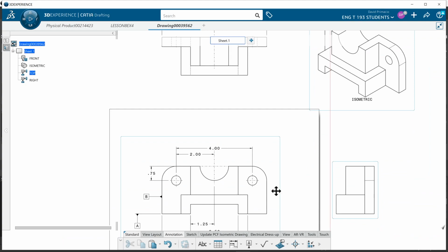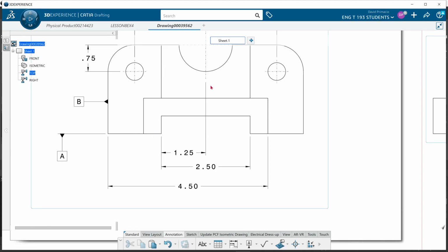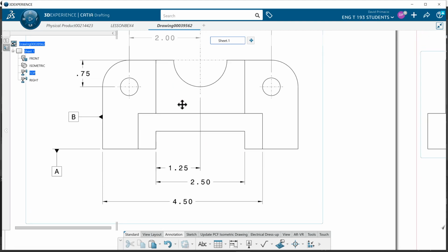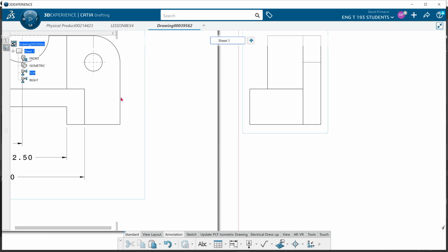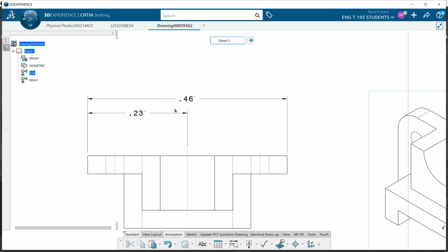Okay, so ANSI ASME specs to hold symmetry. You have to hold symmetry, these holes and these holes, to be symmetrical by dimensioning from the center out and then from the pin to pin or hole to hole. To hold this notch, a dimension from the center to here and then from here to here. That controls that. Okay, and then again up here I'm controlling symmetrical this way.